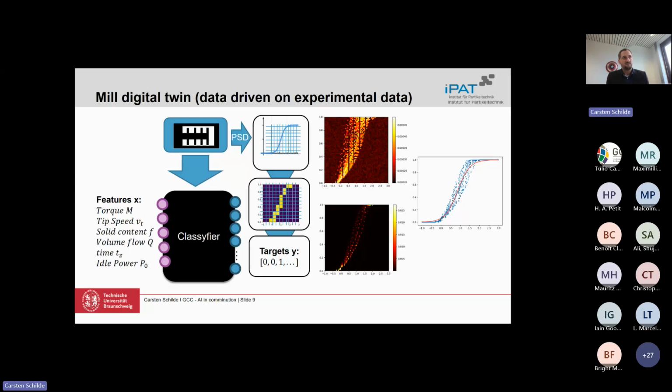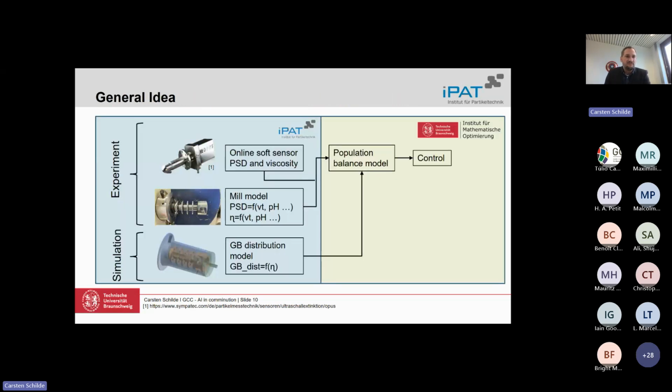And I think all of us know that if we are starting with a certain particle size in a wet milling process, and with decreasing particle size, and maybe at a similar viscosity of our suspension, we can reduce the stress intensity to go further down during our milling process. And that would be nice if we have an intelligent process control that adapts in real time to the given measurement parameters, for example, the tip speed. And with a reduction in tip speed and stress intensity, we get a more energetically efficient process, for example. That's one goal. That means, how to realize it? We need our mill.